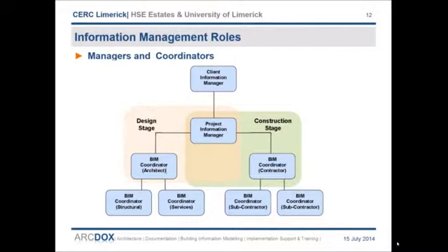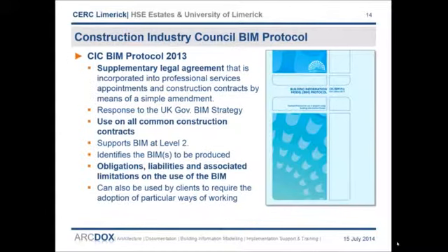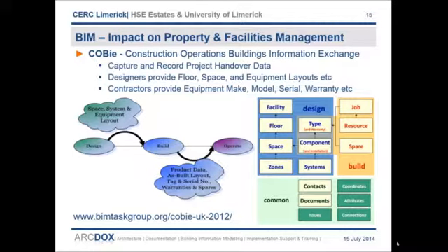An appointed project information manager will coordinate the efforts and contributions of all parties, as set out in the scope. A BIM protocol addendum to the contractual arrangement sets out the rights and responsibilities for the use of BIM to make sure it's not misused. The specification requires all designers, contractors and subcontractors involved in the project to submit at key stages the asset information required by facilities management for post-construction operations in an agreed, structured digital format.